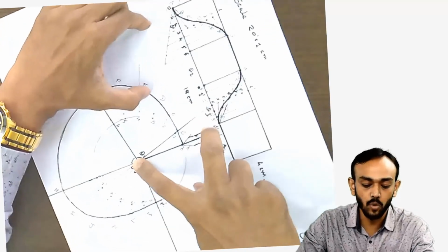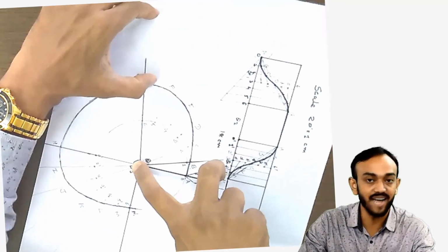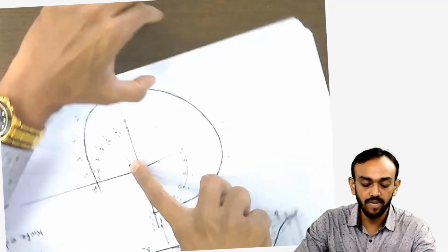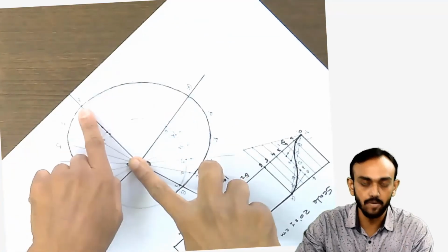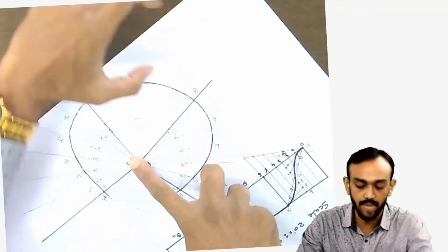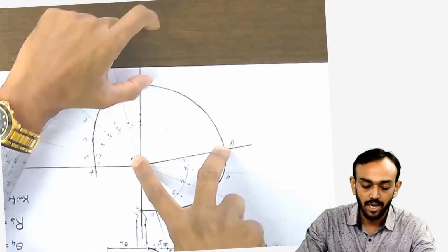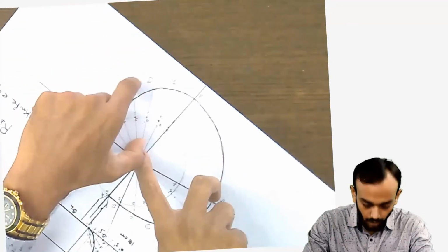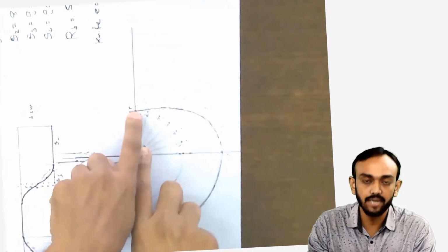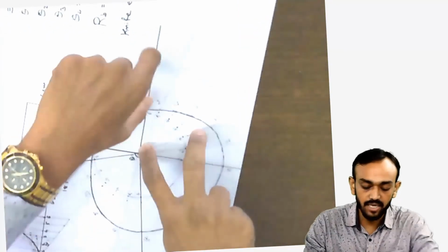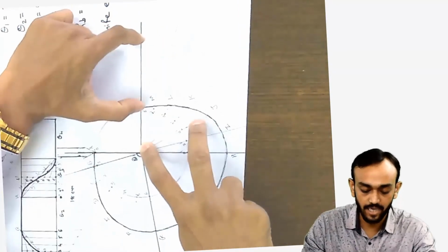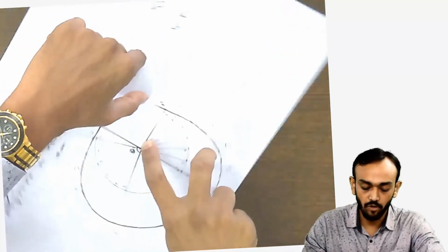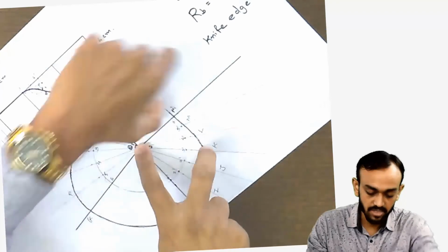The cam is rotating and the follower is moving upward, rise, and then for the next 80 degrees the follower will be in a steady condition, because this distance is the same, so dwell. Then in the next 90 degrees, the follower will move in a downward direction and come back here, and then again theta 4, as you know our follower is right now here. This is the dwell angle, so our follower will be in a steady condition, meaning dwell.